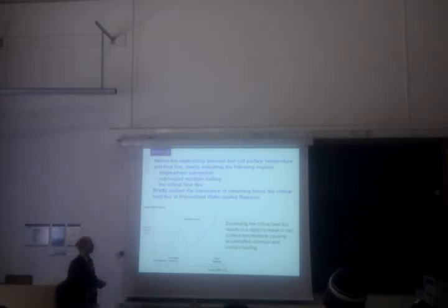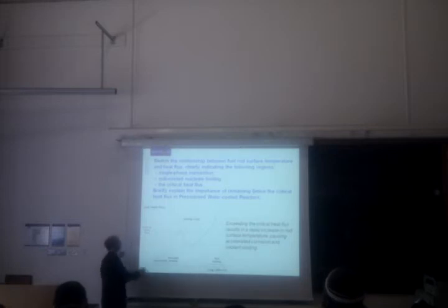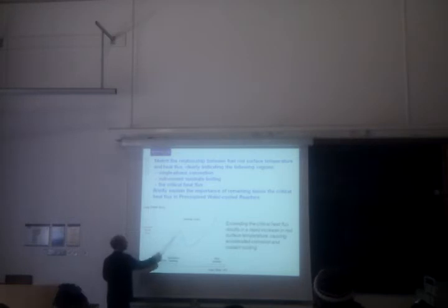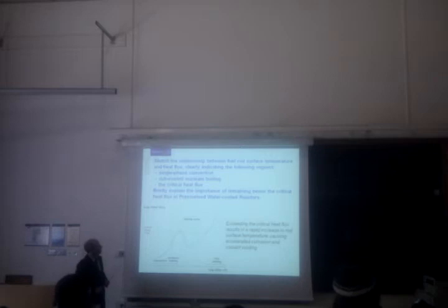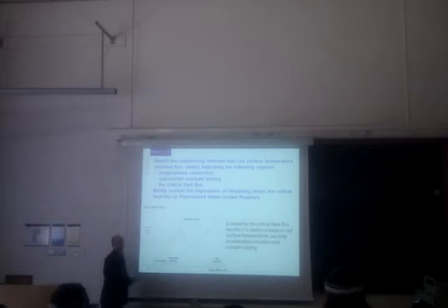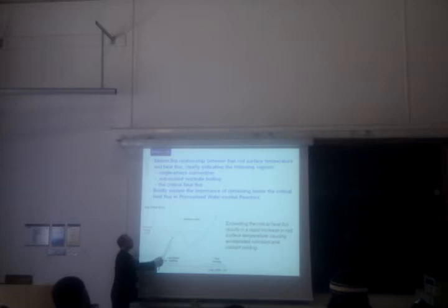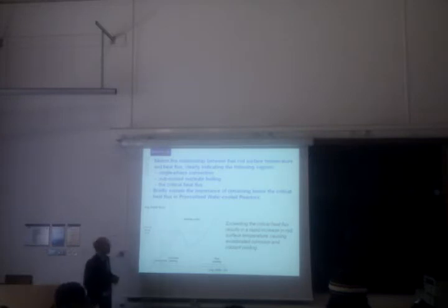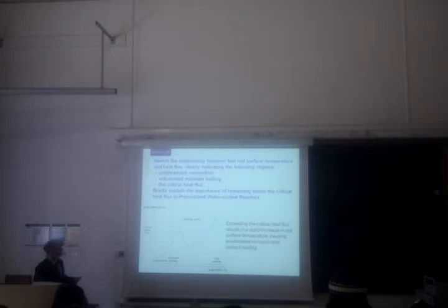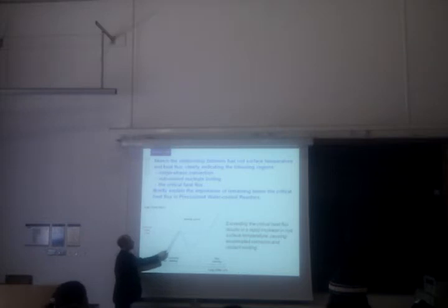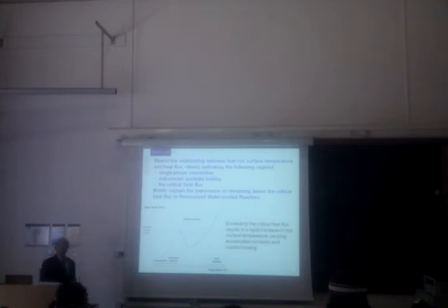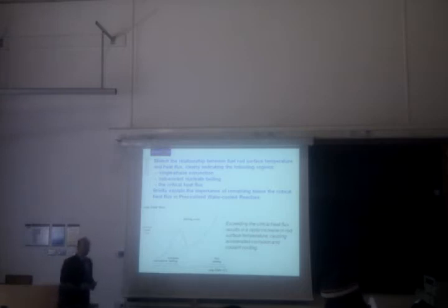So a pretty nice simple question. Quick roller coaster graph. Critical heat flux is the peak of that first point on the roller coaster, and that's the point that we want to avoid going beyond. So for safety reasons, we operate a comfortable distance below that point. And although this particular question isn't asking it, I might have gone on to ask, well, how do we ensure that? How do we ensure we operate far away from that point? And you might be well advised to recall the departure from nucleate boiling ratio as to what it is and what typical values we might operate at.